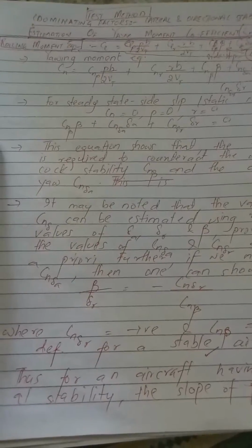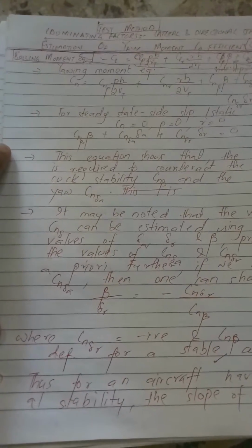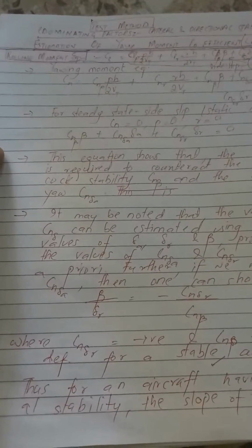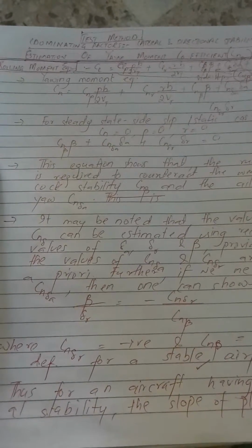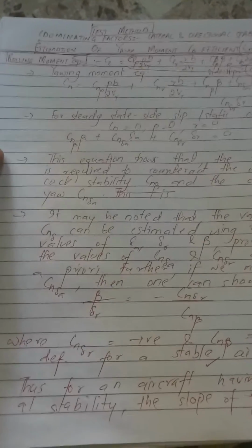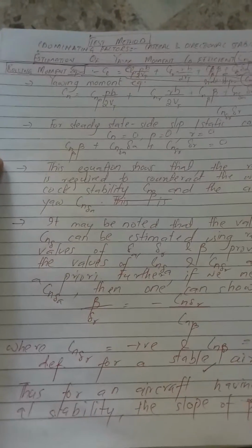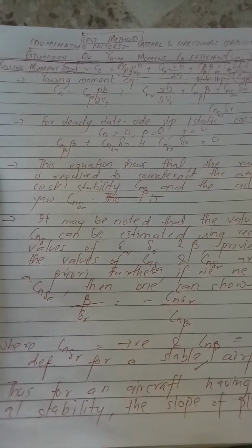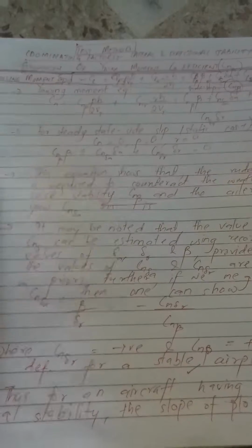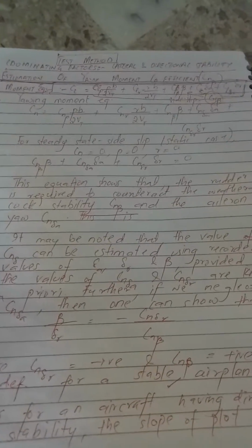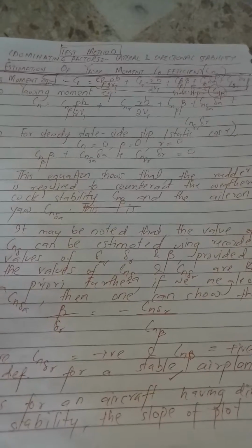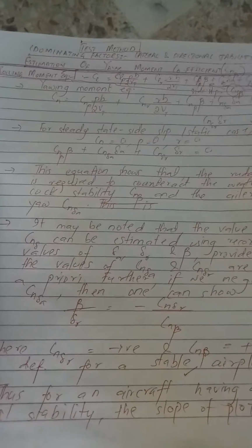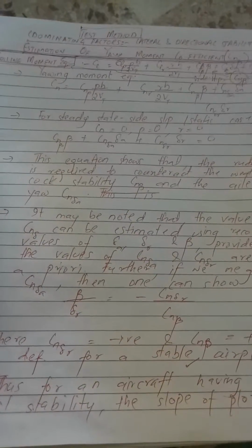So, following the same approach, we're going to implement a test method for estimation of the yaw moment coefficient, which is Cn of beta. In the previous video we talked about the rolling moment equation, which was Cl equals Cl of P into Pb over 2Vt, plus Cl of R into Rb over 2Vt, plus Cl beta into beta, plus Cl lambda A into lambda A, plus Cl lambda R into lambda R. That was for the rolling moment, and that is why we took that equation.